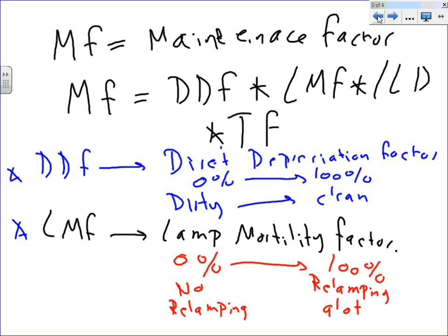So if that flies. If it doesn't fly, I want you to ask Davis and Associates when they come. They take a couple of factors into consideration, and they always get into this: it's too bright. Yes, too bright, because I'm designing not for day one only, but for 6 months, a year from now. Very, very important in terms of light. Unlike the receptacle load, which you would hope stays the same from now until a year or 2 years, and if the load changes substantially, you have to change the circuit and so forth. But light, by design, because they have chemistry working on them, goes down. The lumen goes down in them.